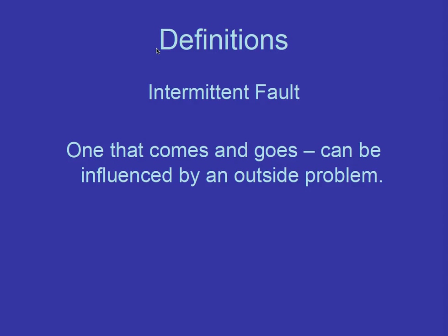If an electrical component in the circuit has failed, or if there is any open circuit or short circuit, then you can find it fairly quickly because it isn't hiding from you. It's a persistent fault that can be isolated by a systematic process of elimination.